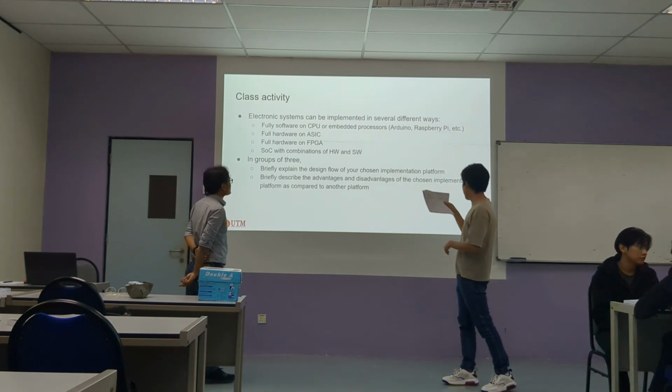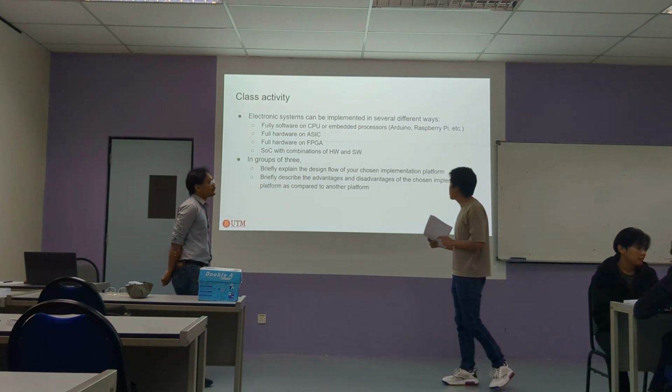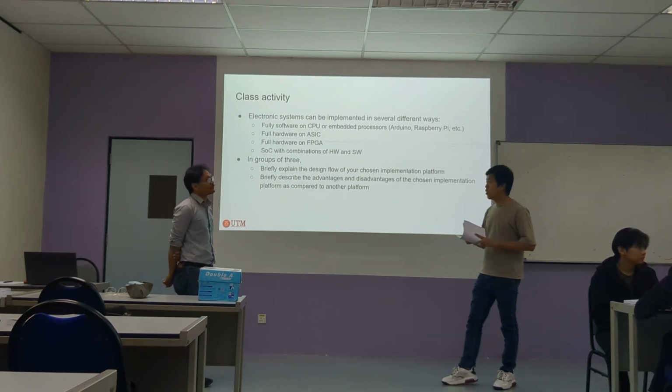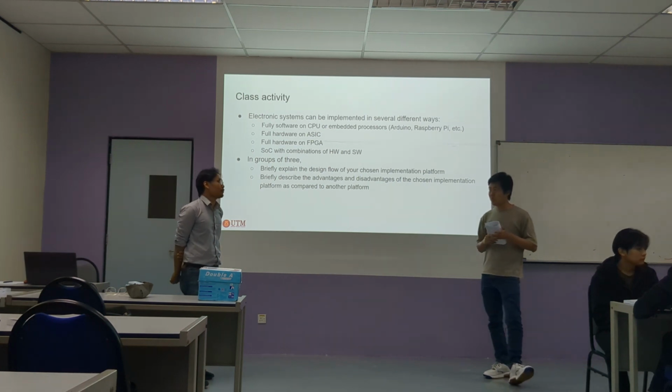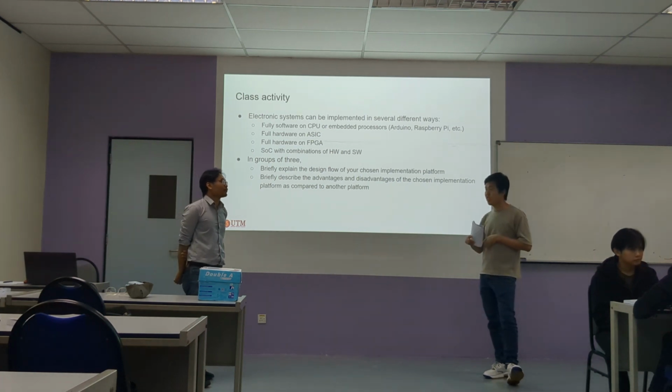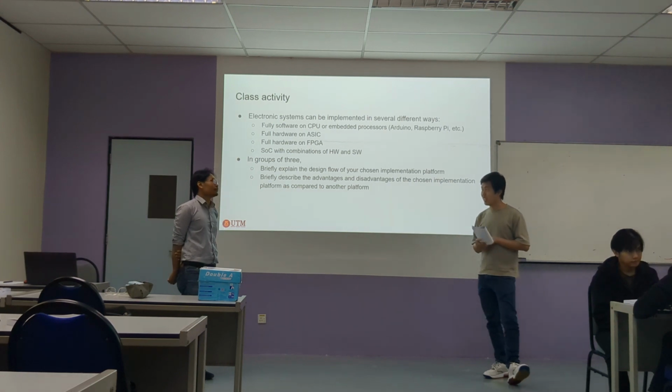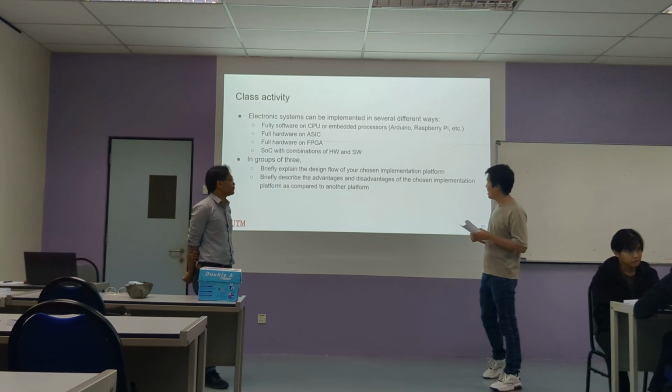Another pro of the FPGA is power consumption. Normally an FPGA is designed for low power compared to the CPU. The CPU has multiple peripheral functions connected to it, so it will consume more power. Even if we don't use them, they are normally activated.